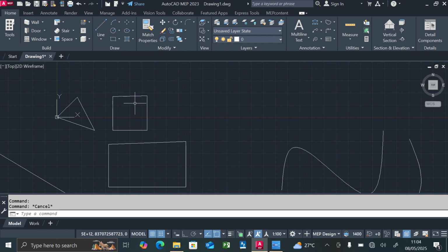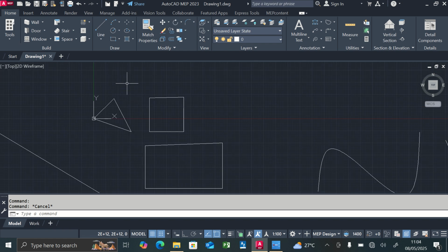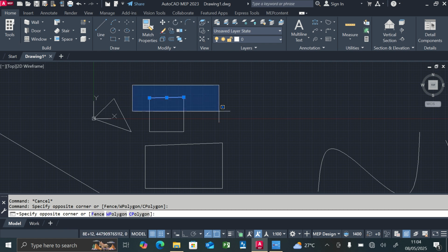So if I drag from the right, it only selects the object which the area of the drag I did covers. It has to cover the full object. Take for instance, for me to select this particular line, I have to make sure I cover an area wide enough to cover the object.